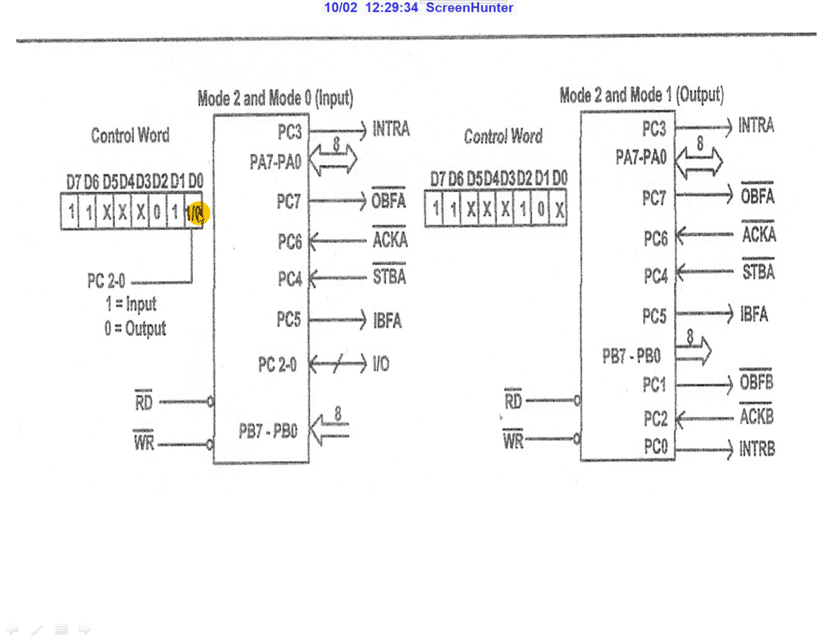Here PC0 to PC2 is going to be given either as 0 or 1, so depending upon the values we give, we set this particular value. D1 is going to be 1 and D2 is going to be 0, and the others are going to be don't care pins.